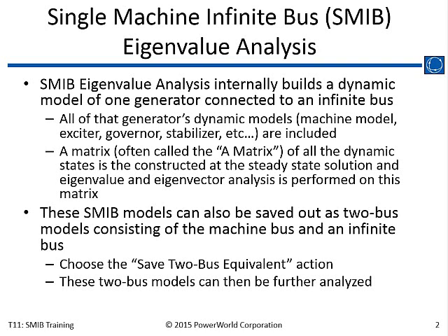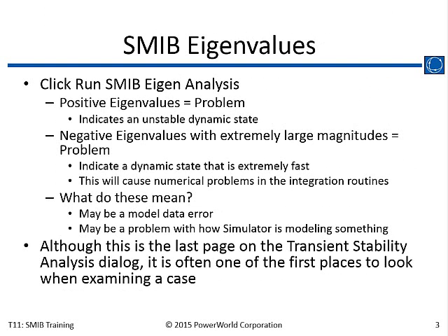Rather, we look at each generator independently, and on the fly, we create what's called a two-bus equivalent for the generator. So it's like the generator is connected to the rest of the system through an equivalent impedance into an infinite bus. So you analyze just the local modes associated with that generator. Okay, and this can be helpful to some extent, but as I said, we don't go looking for trouble. So we're going to show you how to do this.